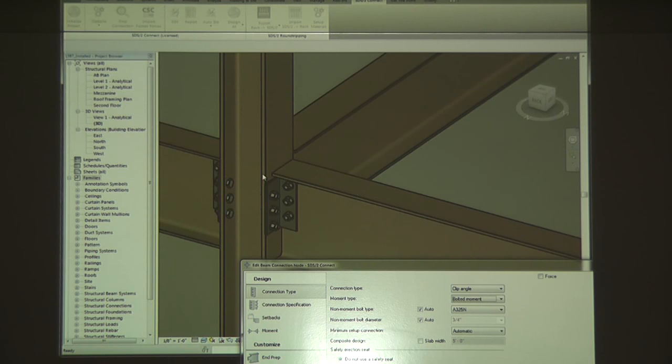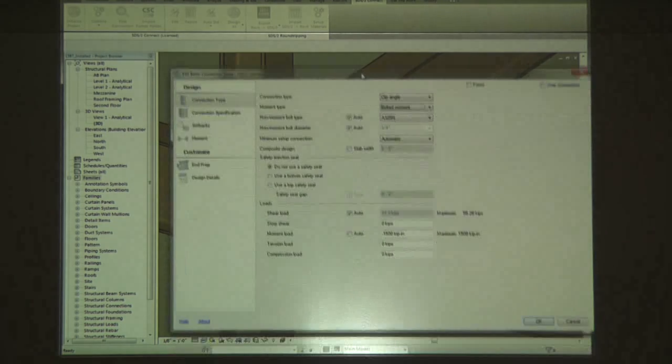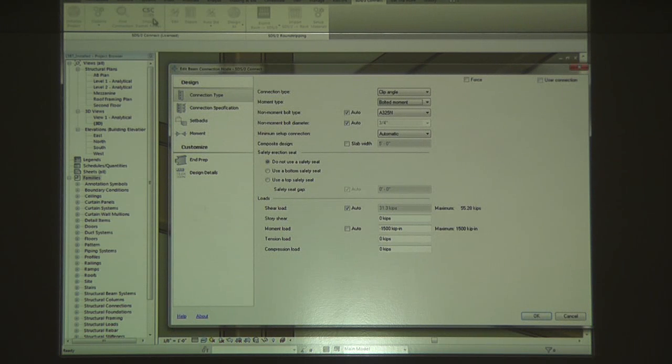Design Data's work is, if this beam is spanning 20 foot or 40 foot, there's a certain amount of weight on there. Maybe rotation, also moment. Well, we read that information in. You can't see that icon up here. We don't have the RAM logo yet, but basically I can read that RAM information in, and it populates this screen based off of what the engineer had defined for loads. So, I mean, that's interoperability at its best right there. Revit, RAM, and SDS2 all using the same database to design connections.